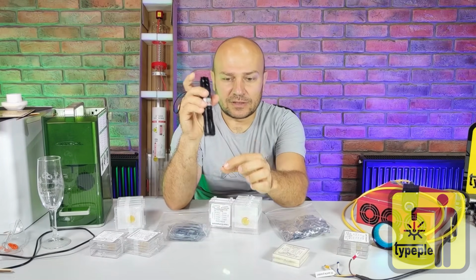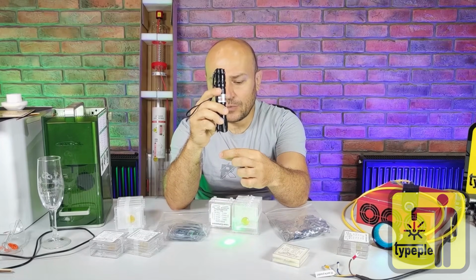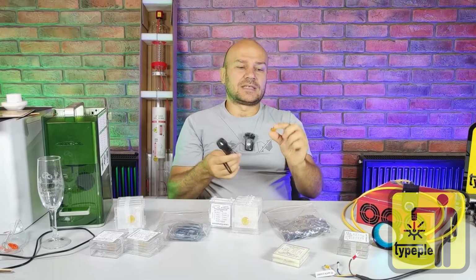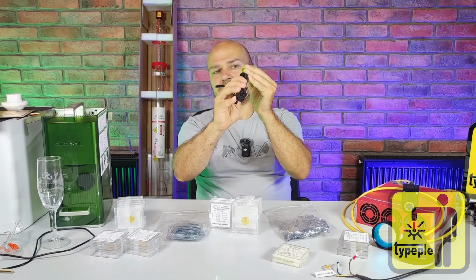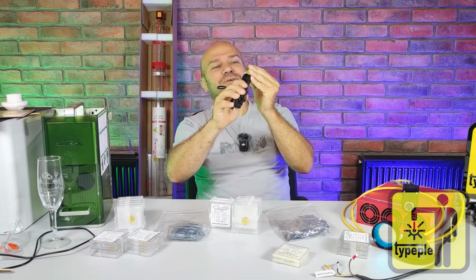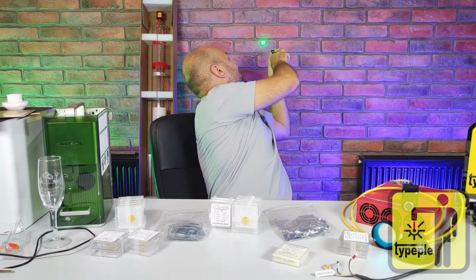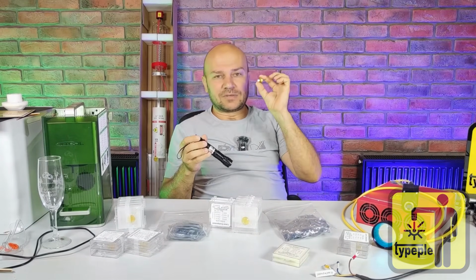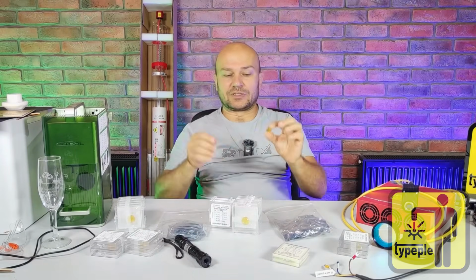If we use a zinc selenide alloy, or in this case, it's a lens specifically for this wavelength, then, accordingly, it's the same situation. We don't get a decent result, or the required beam quality, and our beam just scatters in this medium, in this, let's say, composition. There, I hope you can all see clearly what's happening. The process isn't really focusing this lens well. Yes, there is a focal length. Even if we set it here, shorten it to our 2.5 inches, we won't end up with our beam cutting the table, or marking, or engraving these specific positions.